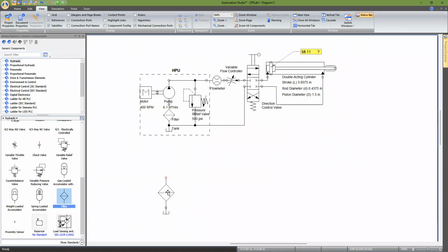If you want to disconnect, you just have to select that thing, press Shift on your keyboard, and then drag it elsewhere. And then you see both ports now became red. So if I now join them again, like that, and leave the mouse button, it just connects.